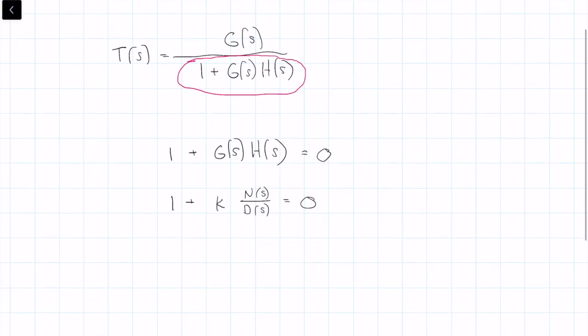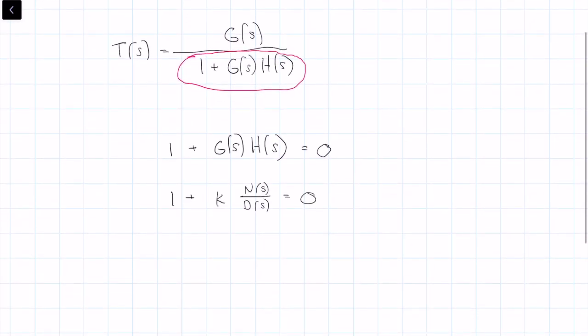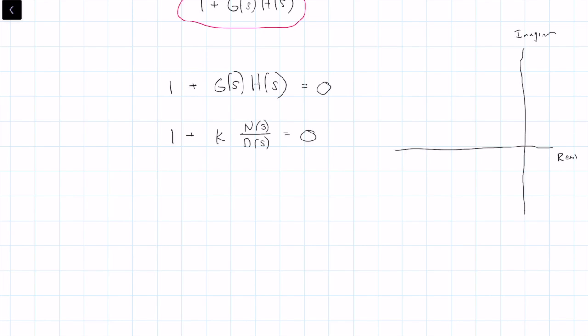Okay, then when we actually get into plotting the root locus, we need to know what the graph actually represents. Okay, so we have usually a set of axes, and we're plotting on the real and imaginary axes. Okay, so we have the real axis and we have the imaginary axis. Okay, and the numerator is obviously made up of a factorized function of some sort that says s plus something, let's say s plus 2, s plus 3, s plus 4, and when we equate those to 0, we call the stuff at the top the zeros. Okay, and at the bottom we call these the poles.